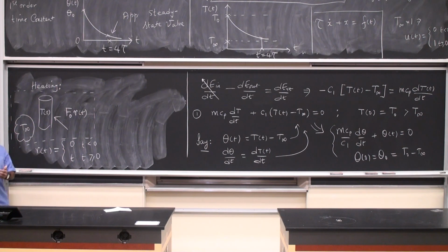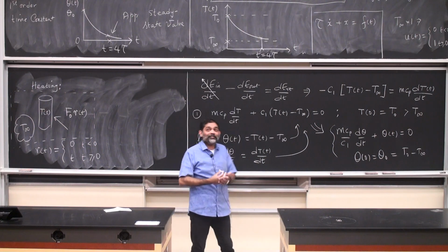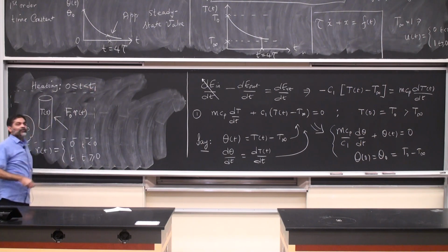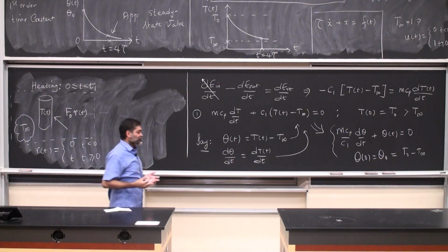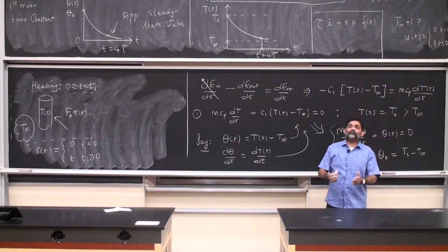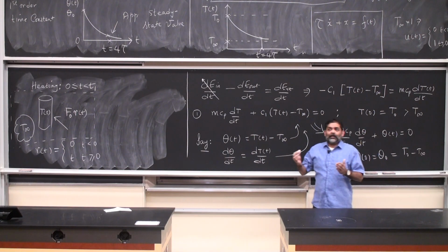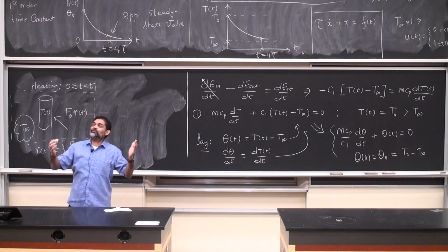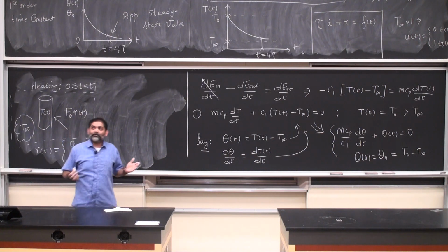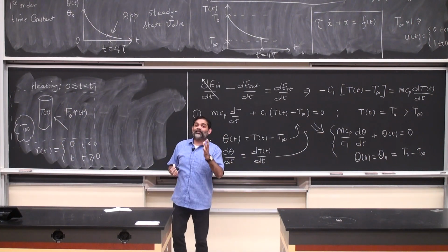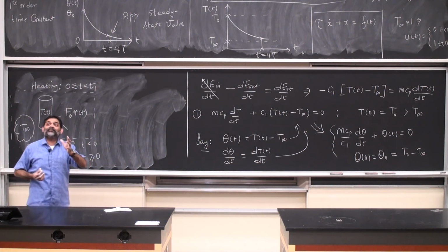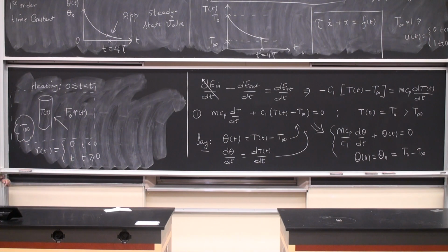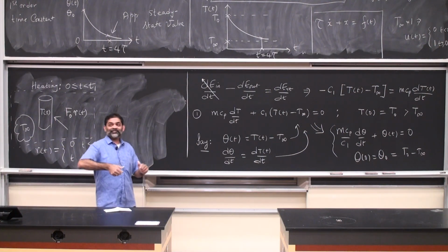This typically occurs for a certain period of time. You don't want to heat this thing all the time, because then you'll just get a mush at the end of the day. So you go from 0 to some standard time T1. The next step in an annealing process is you just let it cool. Let that piece of steel chill, which means it is going to lose heat. You heat it up first by using an external power source, then you let it chill. Why on earth am I doing these things? Because if I do these things, the microstructure of the steel, the carbon grains, they change. And the change in the microstructure brings about a transformation, a martensitic to a pearlite transformation, not important. It increases its workability. You can knead it much better.